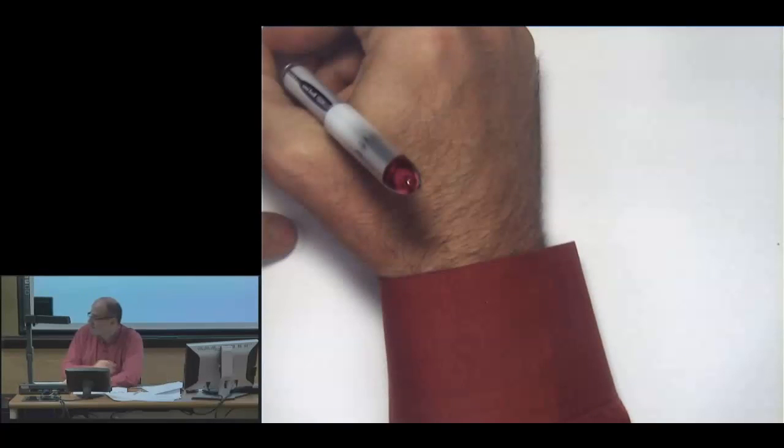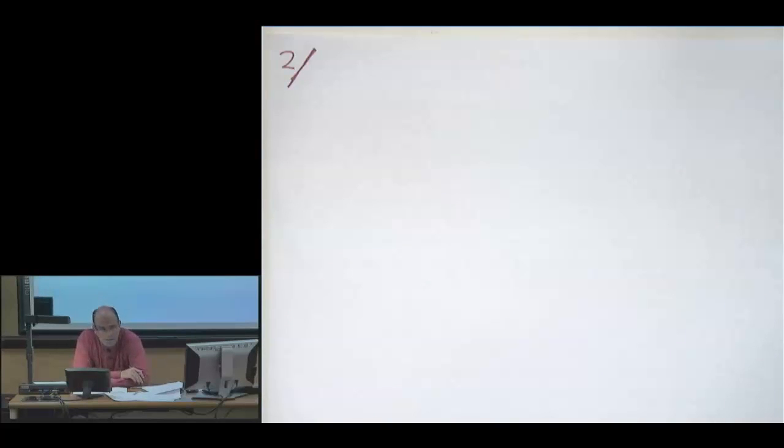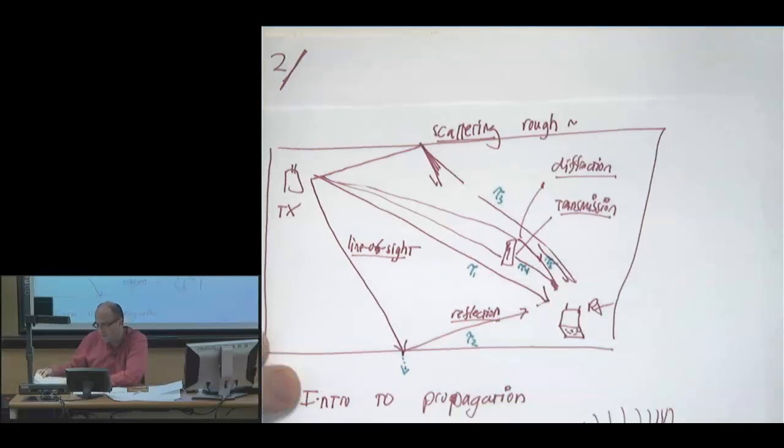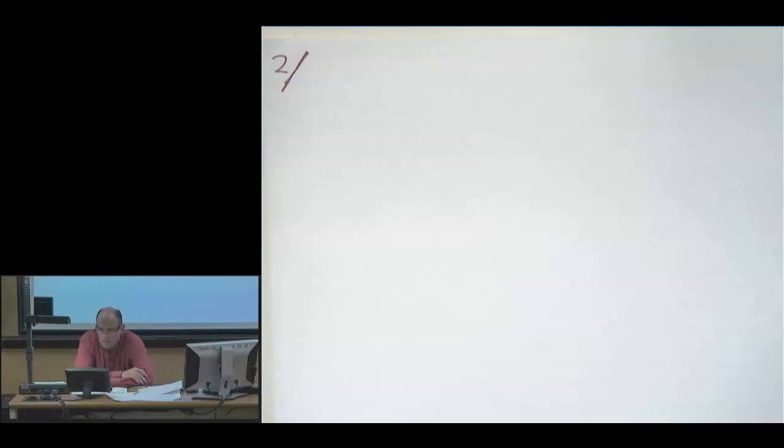Okay, so now there's a whole body of literature devoted to propagation modeling. A big piece of propagation modeling is channel measurement. One of the ways that we learn about the channel is by devising systems that send training data and measuring those impulse responses. And we can measure them in a whole bunch of different places in this room. We can measure it in different rooms. And so that gives us data that we can use to build models here. So we're not going to talk about channel measurement itself. You all are already doing channel measurement in the lab, because when you have a transmitter receiver, you send the training, you're measuring the channel. So there are some other tricky approaches, but that's essentially what channel measurement's about.